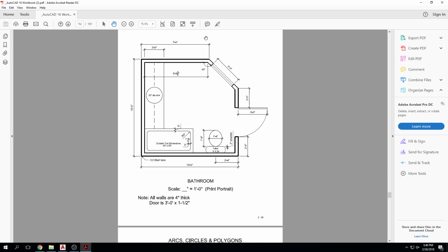I have a question on the text assignment. What is D-text and M-text? Okay, so D-text is, sorry, does it say use D-text to edit? It says D-text right here, but then it mentions D-text and M-text up in the instructions. Okay. So D-text is single line text. It used to be called DD text. And so you'll hear the term DD edit. That's an old term for editing DD text, right? So it's just a little bit of old terminology being used. Okay. If you do it the way I show you, you'll be fine.